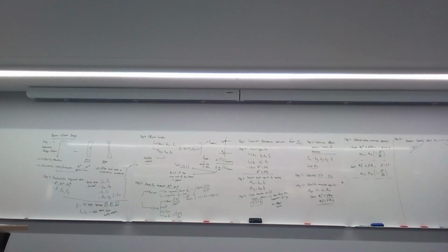Okay, this is a simple check. So if your member is not bending about the x-axis, which means it's bending about the y-axis, then the only thing you have to check is the reduced section capacity Miy, just based on Msy and your N star and your phi Nc. Remember, phi in this case will be 0.9.